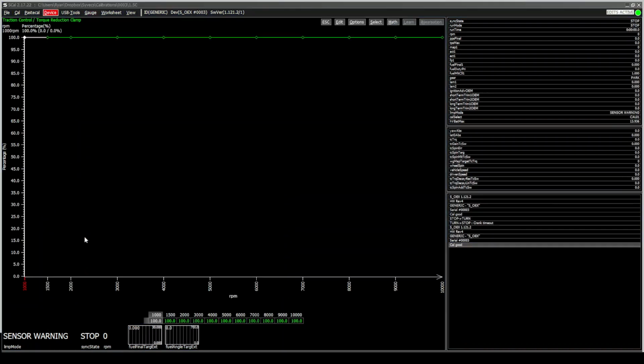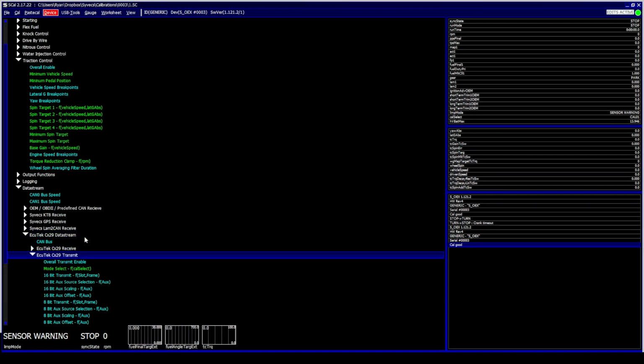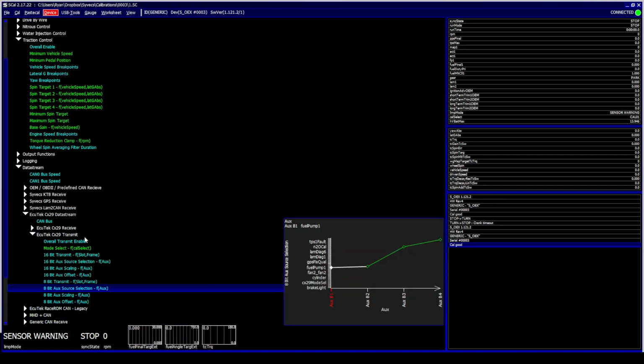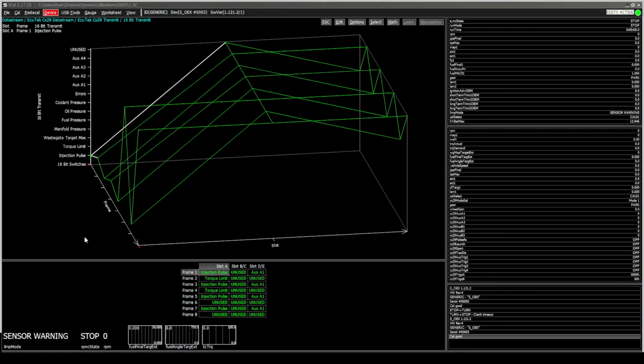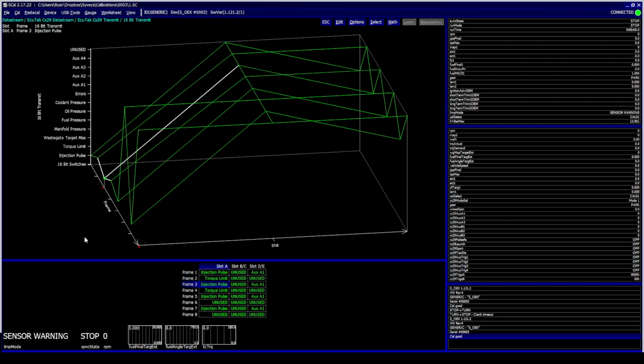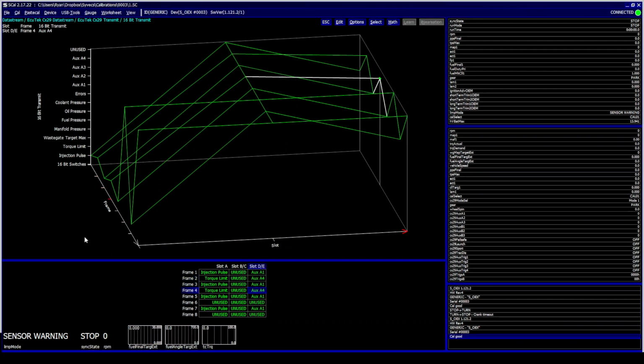Now once you've got that, you can actually then send the torque reduction value from the traction control system, which is called TCTRQ. This is the traction control torque reduction value, and you can then send that over CAN back to the original ECU, which you can then have reduce your torque and stuff like that. So in here, you could assign that to auxiliary 4, which is a standard. Your torque limit here you could set. We've got the torque limit set here already, and then you could assign that to auxiliary 4. So let's say you want to send back the TC torque. We're going to set the auxiliary 4 in here.